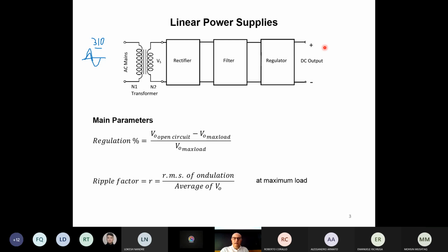Okay, so if I consider that I'm going to, I don't know if this works. Let me show if it works. Fine. If I suppose that basically we will have a resistor placed here, something like this, okay? It's a touch screen. So we usually call it RL, load resistance. When we apply a load resistance to our power supply, we will see that there will be some current flowing through the resistor. Due to this current, usually the output voltage will go down, will reduce, because we are loading the power supply.